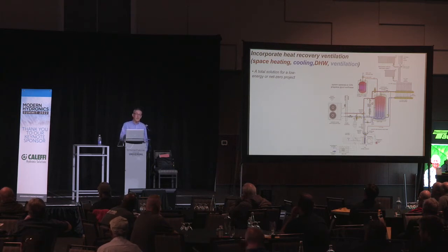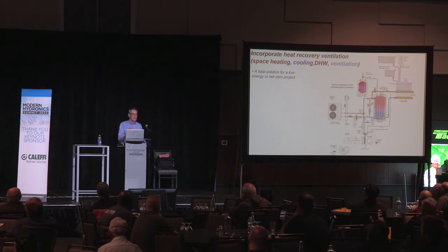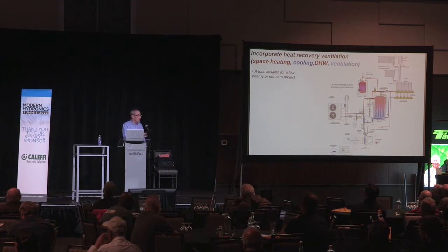The other thing that we can do with ECM blower motors now, we can go from a nominal 400 CFM per ton speed mode in chill water cooling. We can drop that ECM, and some companies will change the programming in the blower for you. We can drop that down to about 150 CFM and perhaps even lower. So we can run that blower motor at a very reduced speed on a ventilation-only mode.